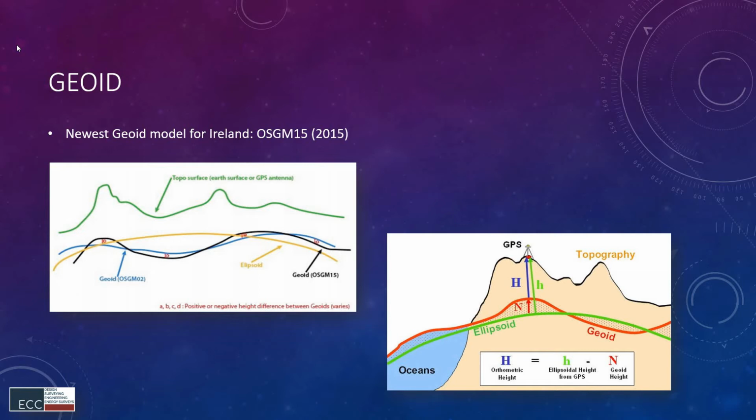Alright, and the other drawing is pretty much the same. We have the reference ellipsoid, and we have the geoid, and you can see the orthometric height. You will actually see these heights in Trimble Business Center, the small h, the big H, orthometric height. So at least you can go back to this picture and maybe have a better understanding. That's it.